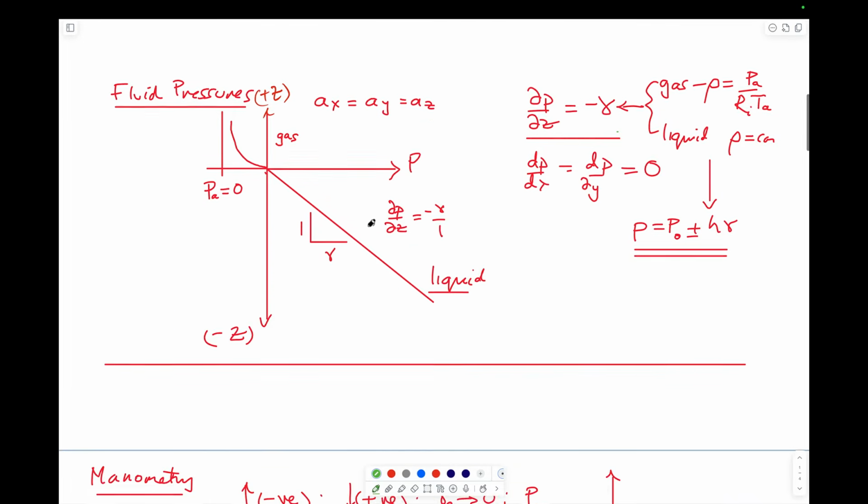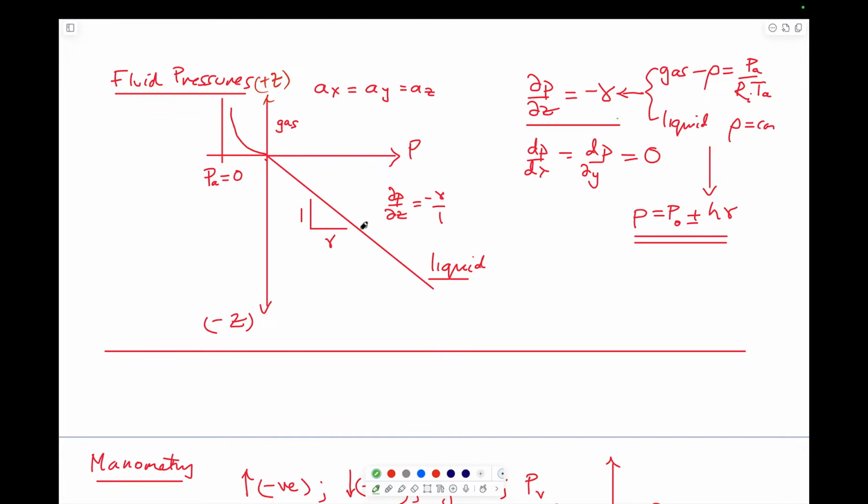We talked about fluid pressures at a point. We know that the important equations are that one that's always true is that pressure changes with elevation and is equal to the unit weight of the fluid, which is the density times gravity. We know that this is always true. We know that there's a minus sign here because our sign convention is for z positive going upwards, and this gives us a value that is congruent for a positive value of a density and gravitational acceleration, which are both positive constants. And so this is just a matter to keep the dimensionality and the sign right on this.